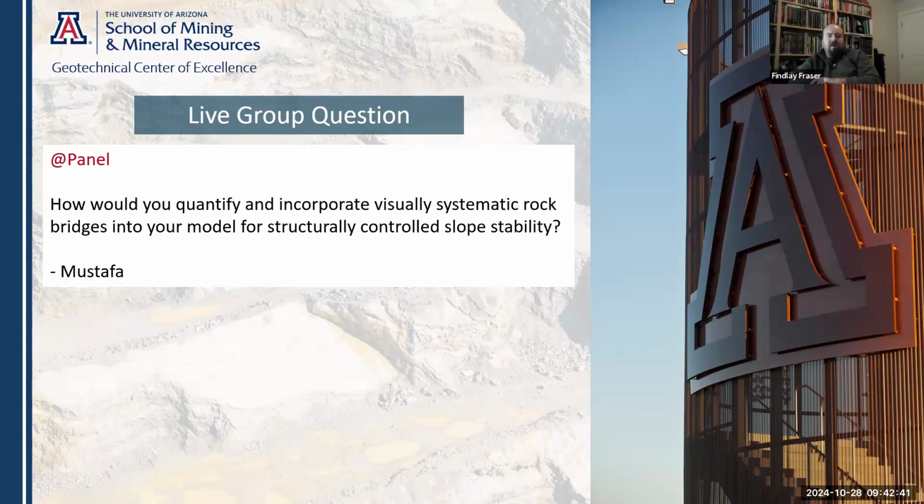But I think the more complex part of that is that typically you're only going to be able to do that once there's actually good exposure. So it really emphasizes the importance of mapping and modeling as your mining progresses, because that level of detail, being able to see those rock bridges, you can't do it from drilling. It's not those three structures that are defined. We would probably just turn them into one based purely on the drill holes. So what this question emphasizes to me is the importance of mapping and constantly gathering that information about the structures as you're exposing them.